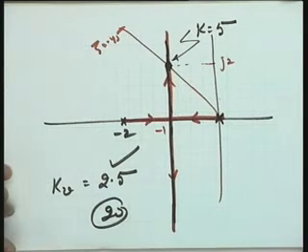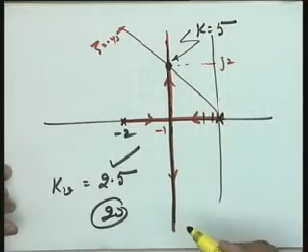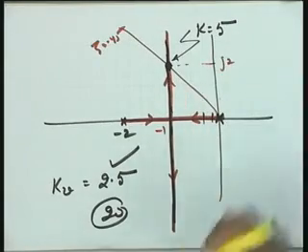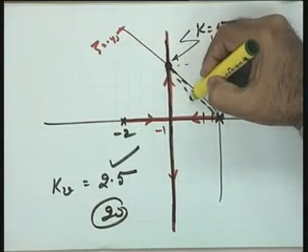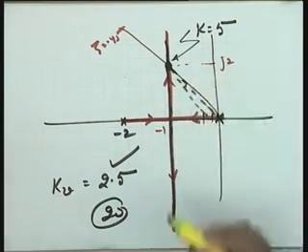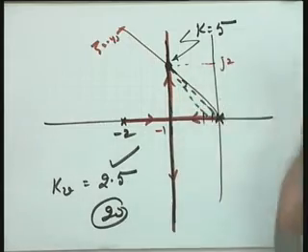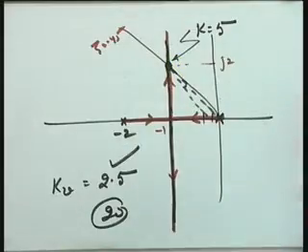So what I do in this case, I place the zero and the pole very close to the origin so that the net angle contribution due to both zero and pole is negligible. The pole and zero angles are negatives of each other, so the net angle contribution is given by the pole-zero pair, and if this net angle contribution is 1 to 5 degrees, this pole-zero pair is not going to disturb the root locus.